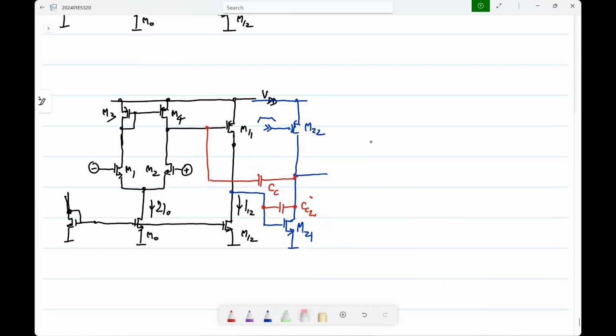So this is what is called a 3-stage Miller compensated op amp. Sometimes it's also called nested Miller. Nested means one inside another. So that's basically what it is. And you can keep going. Now you know how to design this at the level of GMs, so you can keep extending this.